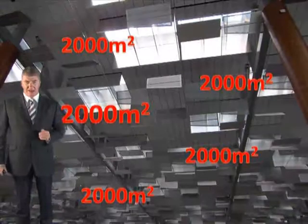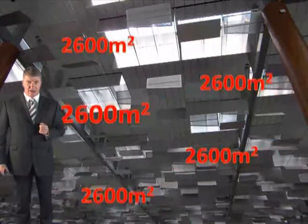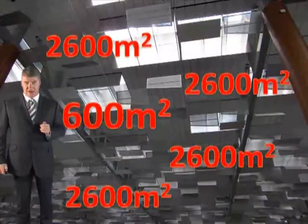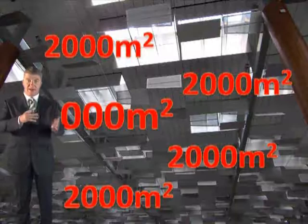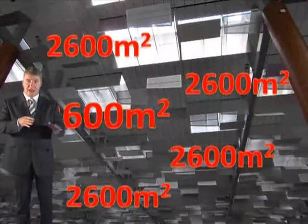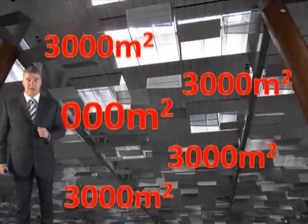Now, the general limit is 2,000 square metres if it's got natural ventilation, and it's 2,600 square metres if it's got mechanical extraction. However, if the primary objective is not life safety, but primarily property protection, then the size of the reservoir, whether it's natural or mechanical, can be increased to 3,000 square metres. So if it's purely for life safety, then it's 2,000 and 2,600. If it's for property protection, no life safety implications, you can increase it to 3,000 square metres. And this applies to nearly all types of occupancies.